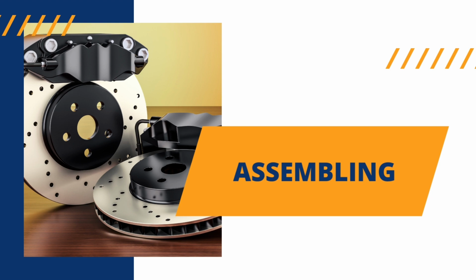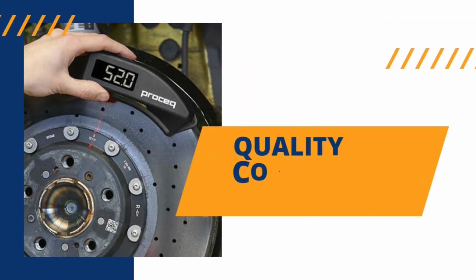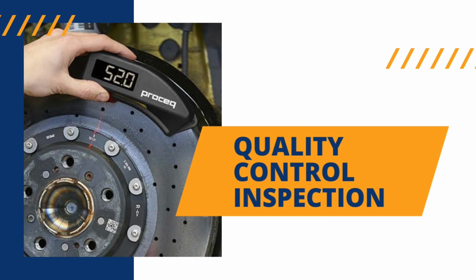After the retention nuts are properly torqued, each fastener is marked with paint to indicate that the step has been completed. The last step is quality control inspection. During a quality control inspection, the finished brake rotor's lateral runout and other pertinent dimensions are verified. Various pieces of information, such as batch number, to provide a means of tracking the rotor in the future, minimum acceptable mass, and minimum rotor thickness are printed on the metal hat.